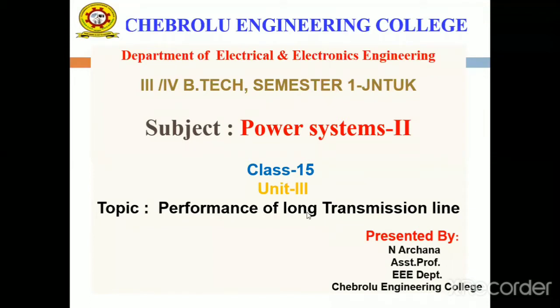Each method has its own equivalent circuit diagram and separate phasor diagram. By using the equivalent circuit diagram and phasor diagrams, we easily determine the efficiency, the voltage regulation, and also the sending and receiving end voltages.